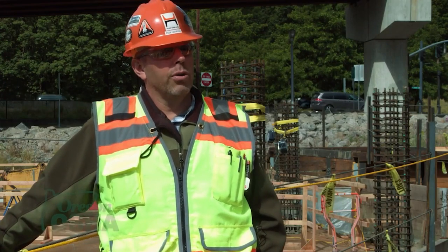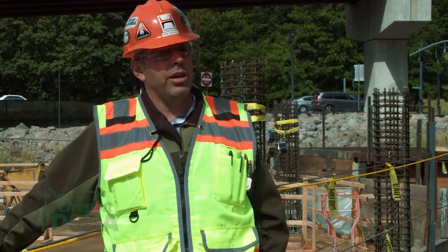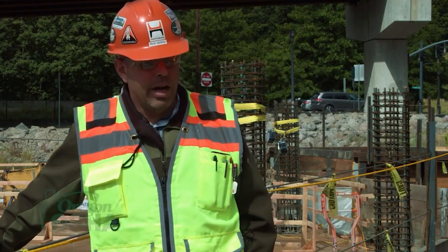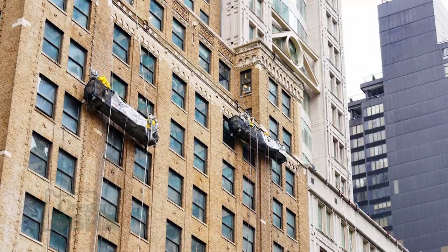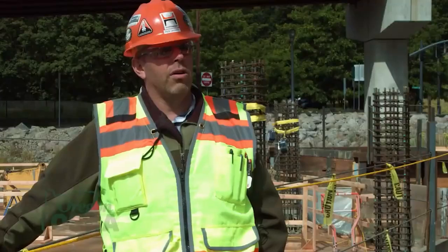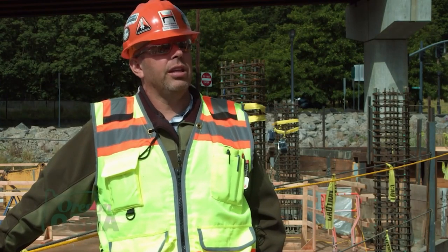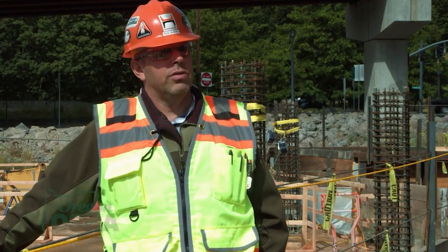That if you exceed the 4-to-1 scaffold height, your scaffolding is tied back into whatever structure you're working off of. On swing stages, there's a whole different set of rules that go with them. I would say on swing stages, you want to make sure that you have primary and secondary fall arrest, and that your fall arrest system for your workers on your swing stage is completely independent of the swing stage itself.